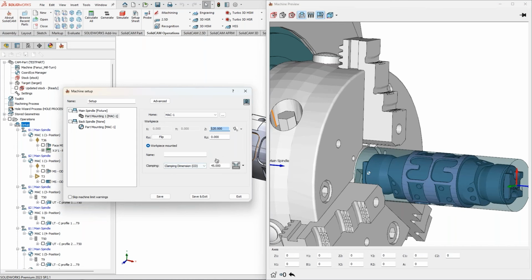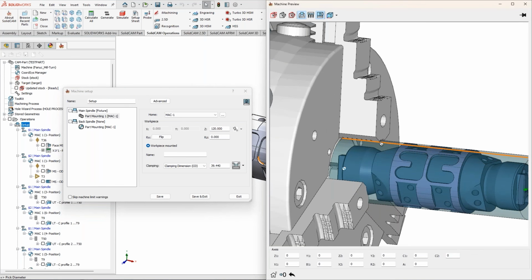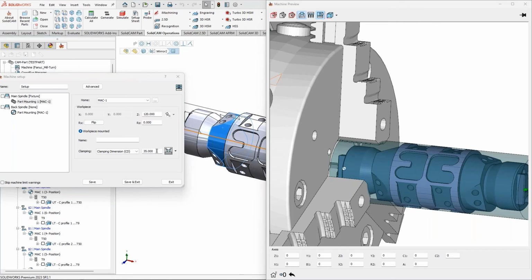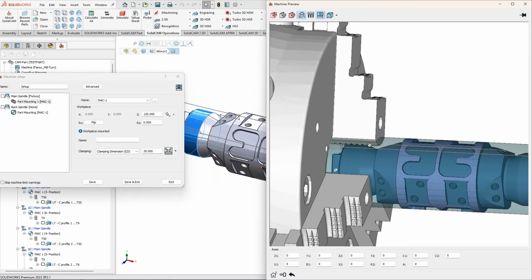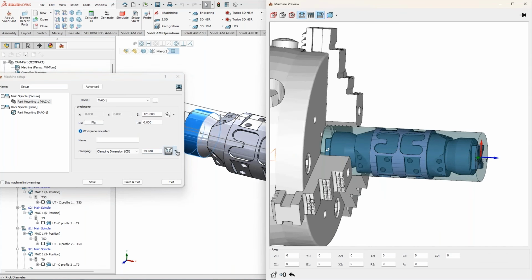This is my clamping that we pull from the toolkit. And now you can just close on stock, and we automatically close on this specific stock. What you can also do is click on this diameter, and you can click on any of these entities, guys. It will close on this. You can also use the option of close on target.